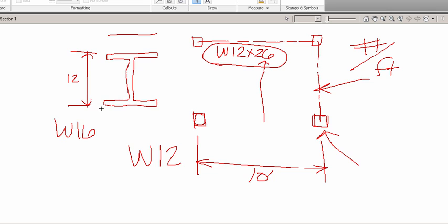So steel beam, how would you know what width it was? Well, you'd have to use some charts and manuals to find out what wide flange dimension this is. And there's plenty of those out there. But this is probably the most crucial component to the whole system, is the weight of the beam and how tall it is. The height gives you some head clearance for sure, and this is structurally important because this is how you're going to put the thing together, how much it's going to weigh on its own.